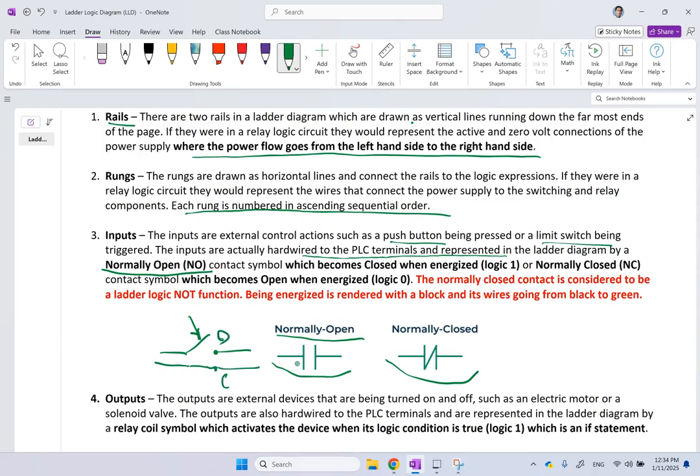So you go from open to close. But by default, it's open. You have to press it to make it closed. Many of the push buttons are like that. On the other hand, we have some switches that by default are closed. You have to apply some voltage, force, or torque to make them open. So by default they are closed, but you can force them to be open, okay? So they are normally open or normally closed depending on their default situation.